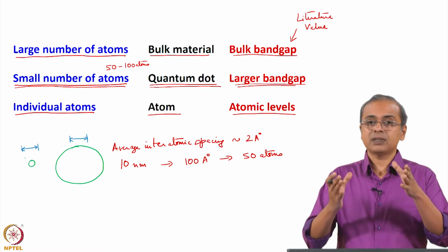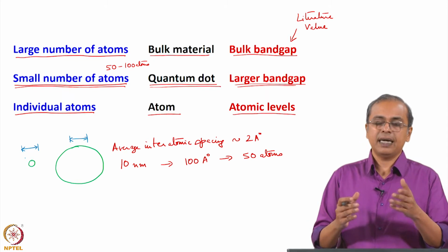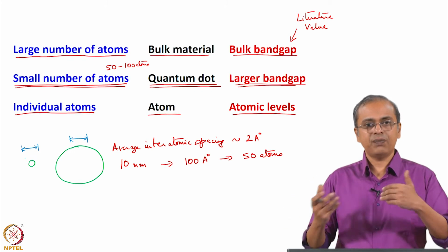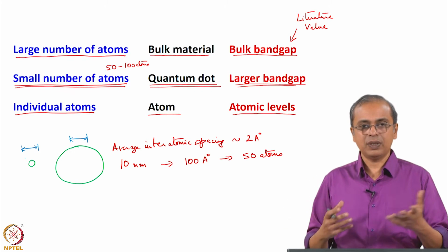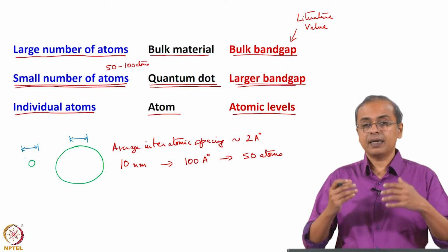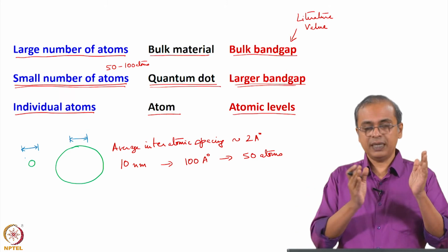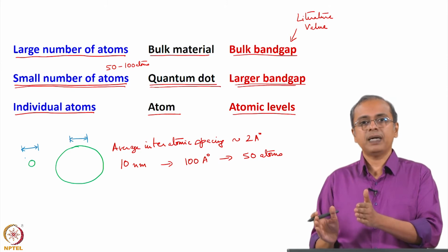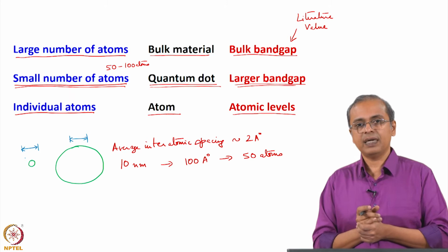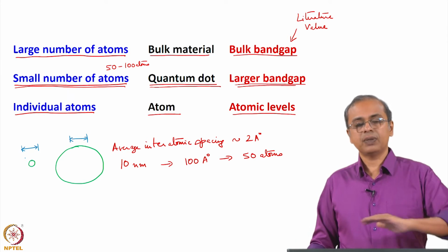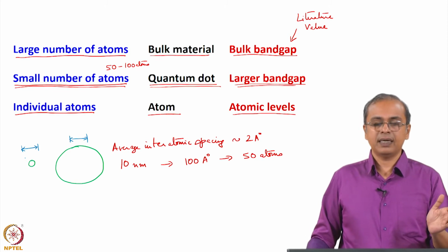So, if you are trying to make a solar cell and you have dissimilar materials present there, then each material may expand in a different way, the cell may crack, and then you will eventually not have something that is working. But if you want to absorb the entire spectrum, the infrared part, the visible part, as well as the ultraviolet part of the spectrum, then you do need a range of band gaps, so that you can capture this entire spectrum effectively.